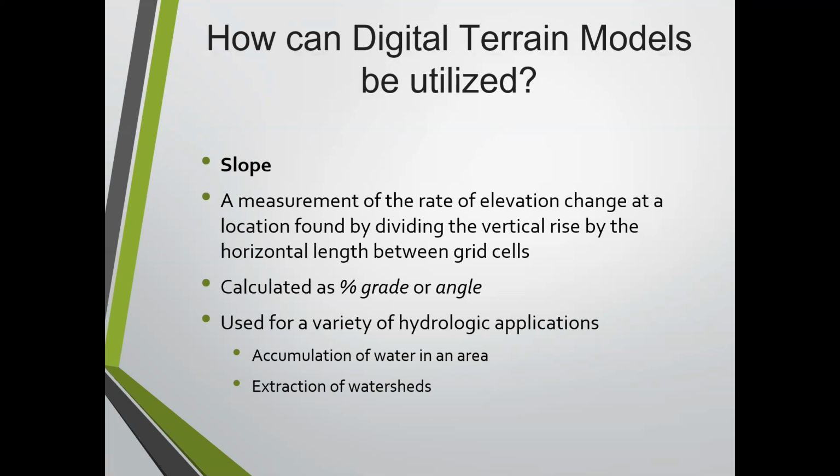So a watershed, I think most of you understand what a watershed is, but it allows you to determine the drainage basin area. Each creek that you have is surrounded by basically an area that it's catching the water. Then you get to a ridge, and the ridge on the other side is going to be another drainage basin. All of the software that I've ever used has the ability to go in and calculate watersheds for you. That can then be used as the area for hydrologic calculations of pipe sizing and culverts and all that kind of stuff. You need to know how much water is coming into you, so that's determined on the watershed.